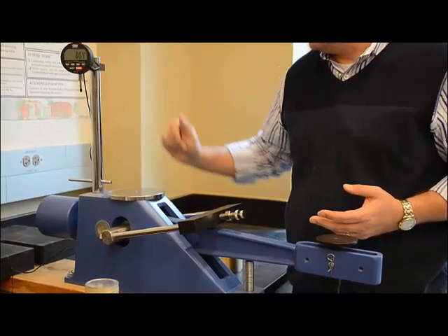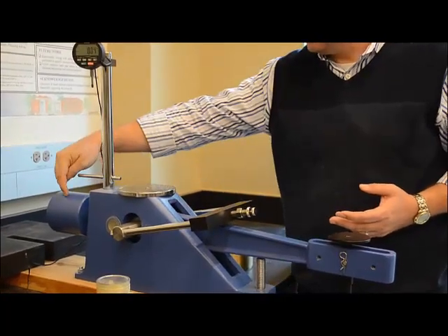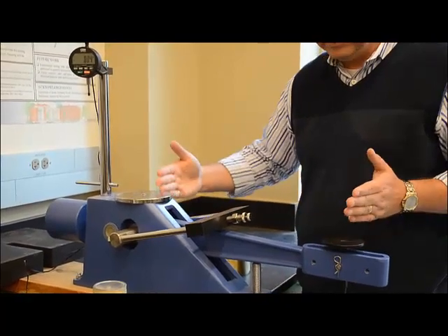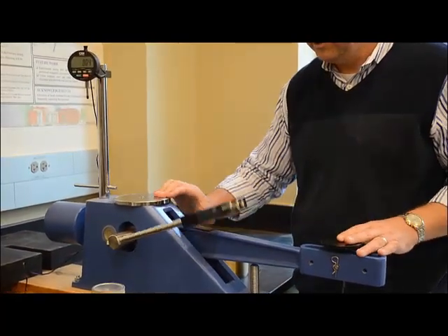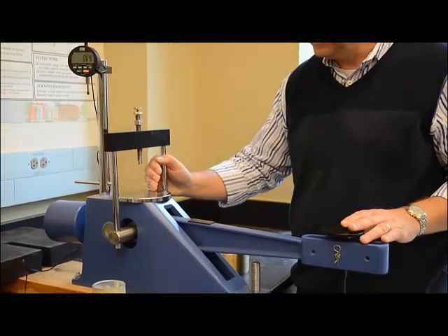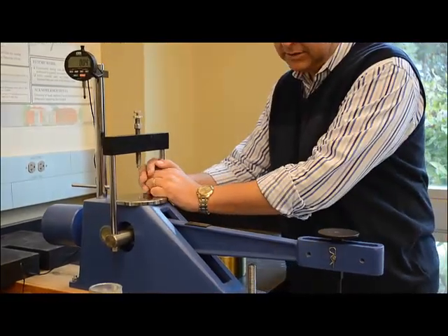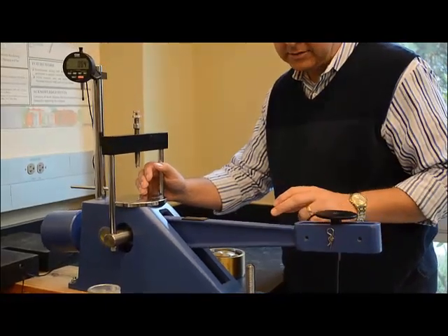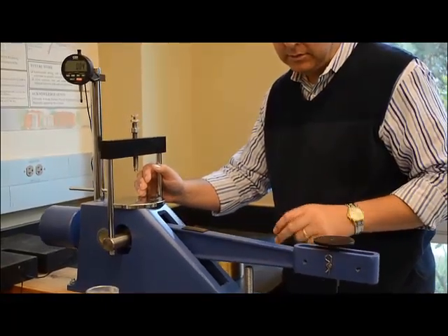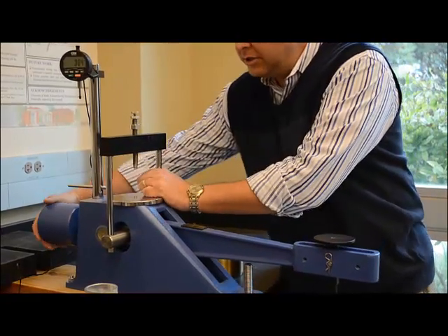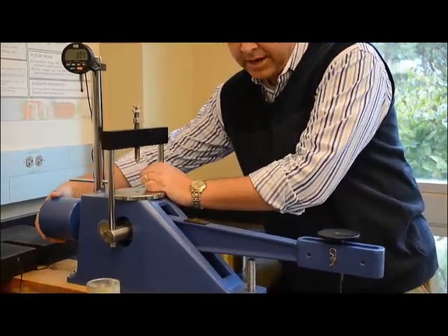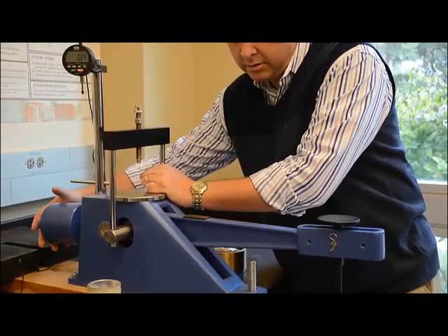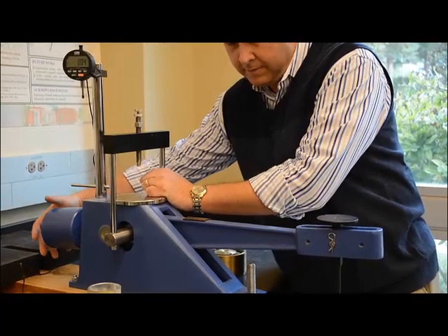This is the consolidation apparatus itself that applies the load. It has a counterweight there that I'm pointing to. That's the platform the soil sample will sit in, and notice that the distance there is appropriate for a 10-to-1 ratio, meaning whatever load is placed on the lever is 10 times the amount of weight that the soil will feel. I'm calibrating that to make sure the counterweight is in the appropriate location, so whatever load we place on that hanger is indeed the amount of pressure felt by the soil sample itself, and that can be adjusted as I'm doing there.